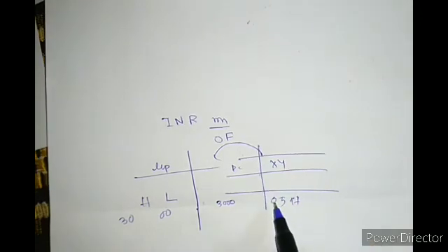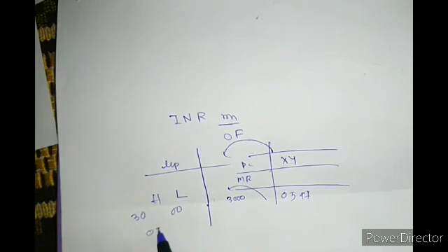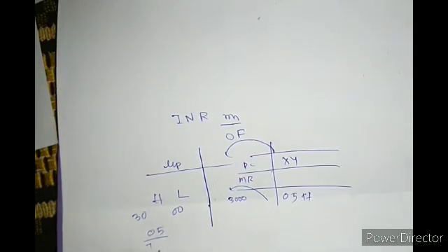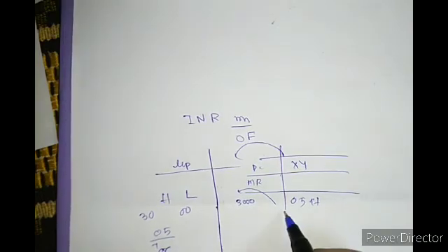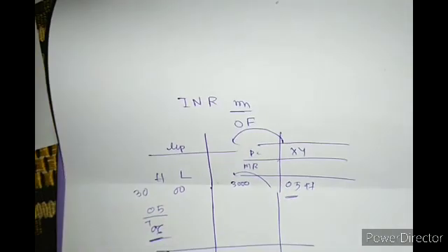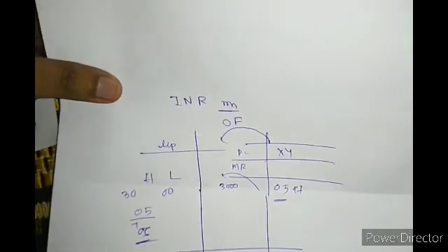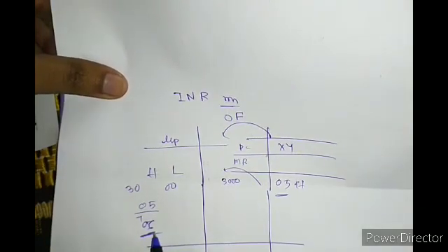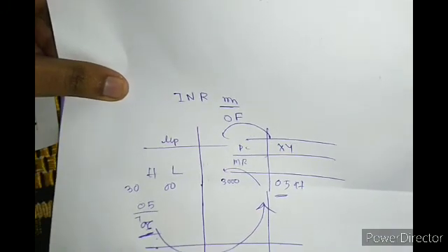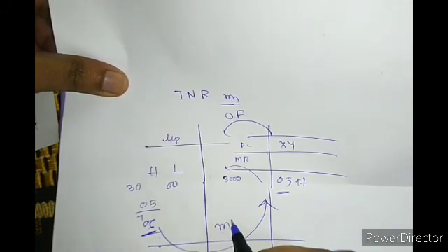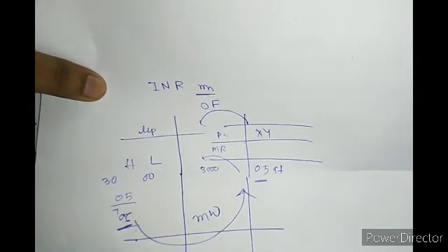When we are reading something from memory, that's an MR operation, right? 05 comes here, the accumulator increments it, now it becomes 06. Now, this data needs to get changed also. This is what my instruction says, right? I have to increment the data. So from this, 06 has to get stored here. So when the MUP is giving data to memory, this is memory write. Do you understand what the point is?